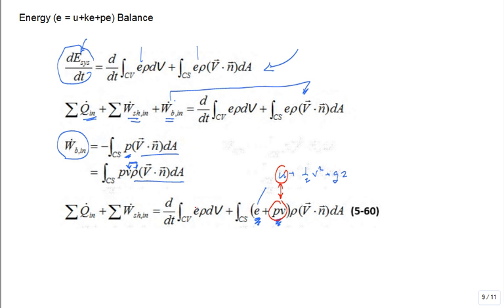This one right here doesn't have enthalpy in it, does it? But when it flows across the boundary, you have this boundary work associated with deforming a control mass, which you push over and put into a new property called enthalpy for the mass flow rate across the boundary. Here is our shaft work, here is our heat transfer, here is accumulation or depletion of the control volume, and here is the flow in and out of the control volume.